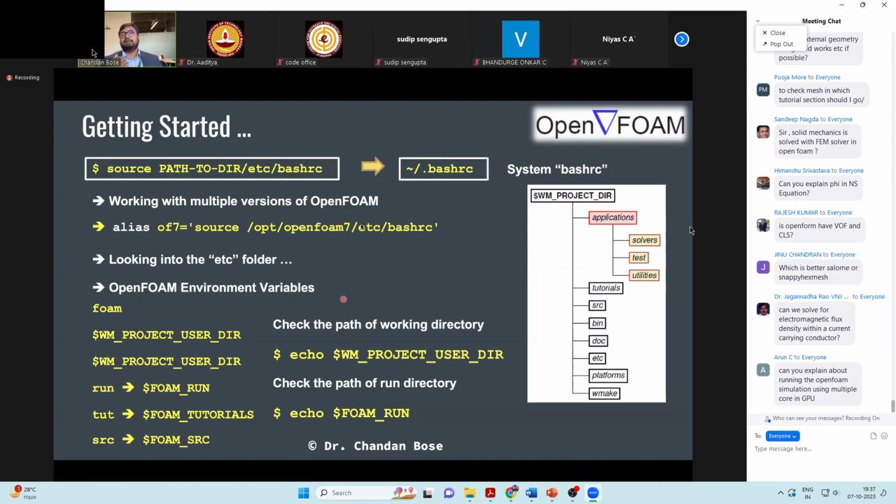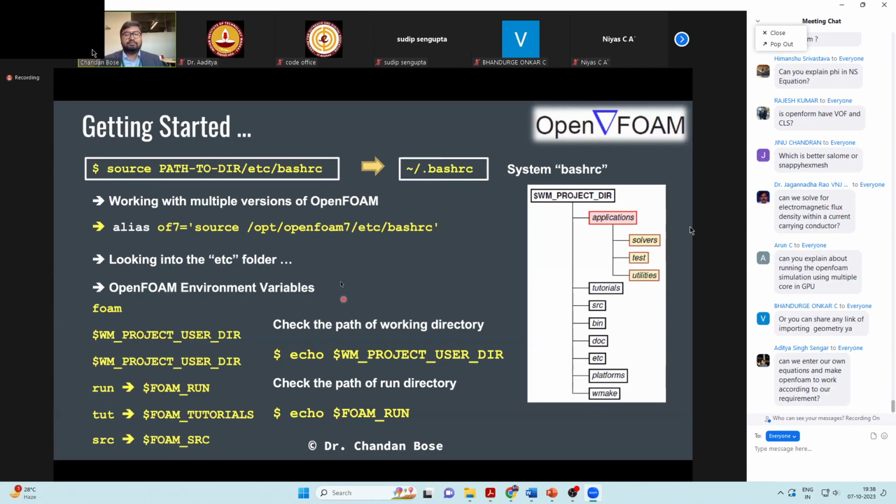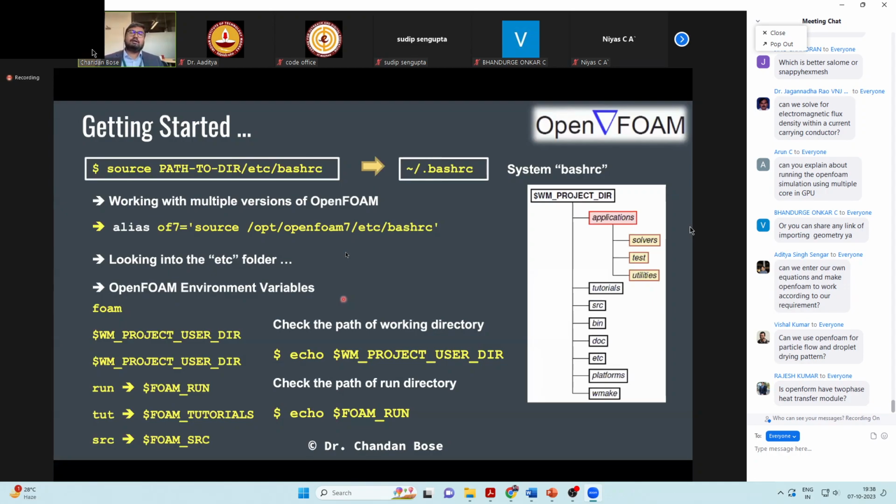So I am just telling you as a fact that suppose you make your geometry in ANSYS Fluent, what you have to do is export the geometry in the ANSYS Fluent format, and then you use a command to convert it to the polyMesh directory, which is, for example, fluentMeshToFoam. Okay. So I'm just writing here if somebody is interested, but I won't be able to cover it today. So this is the command that you use to convert an ANSYS Fluent mesh into a polyMesh directory. All right.